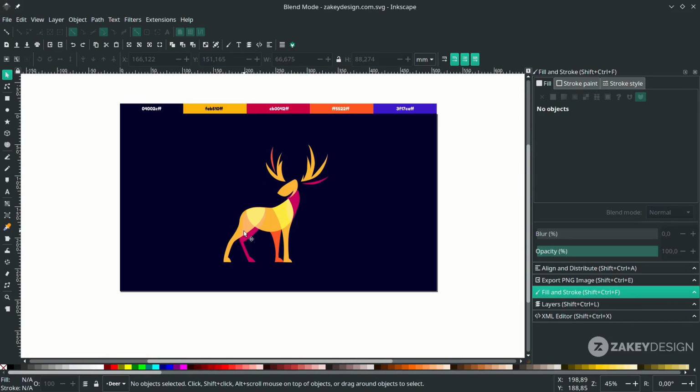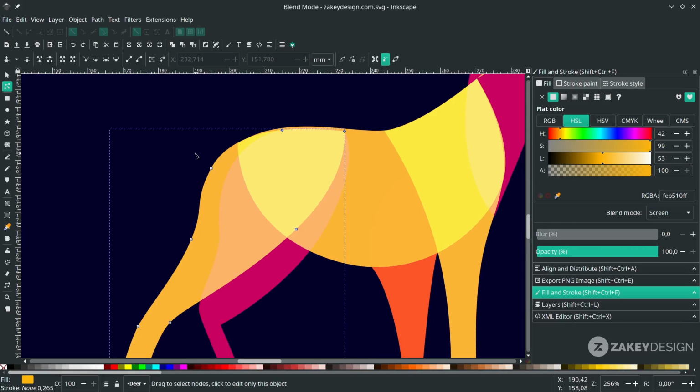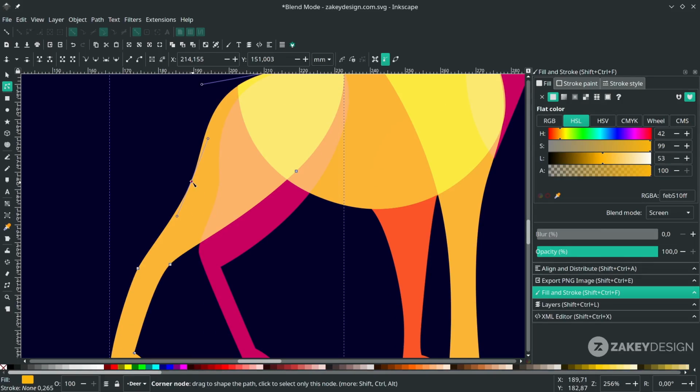Refine it to make it smooth by pressing F2, then click. You can delete this knot. Press Delete. Just remember, the last knot is the smoother. Right? Bring it on here. And this too, you can drag it.